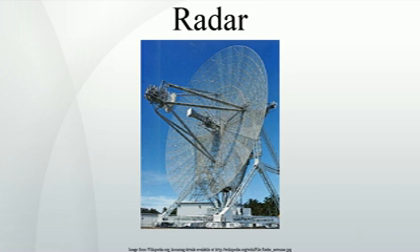Side lobe jamming can be overcome by reducing receiving side lobes in the radar antenna design and by using an omnidirectional antenna to detect and disregard non-main lobe signals. Other anti-jamming techniques are frequency hopping and polarization.